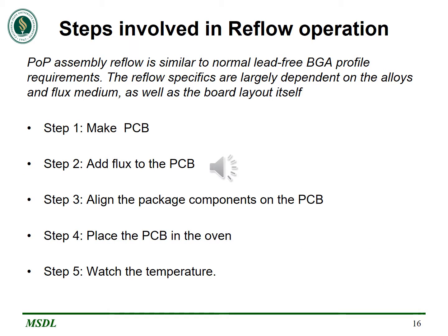Next, we are going to discuss the steps involved in the reflow operation. Package on package assembly reflow is similar to lead-free PGA profile requirements. The reflow specifics are largely dependent on the alloys and flux medium as well as the board layout itself. The first step involved here is to design the PCB board.